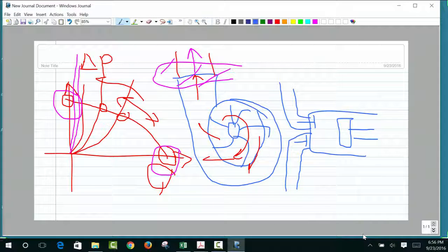Gear pump, the pump that drives the fuel in your car. All those pumps take a fluid, trap it between walls by closing the valves and the piston, then open this one and push the piston. The fluid does not have a choice but to go out, right?